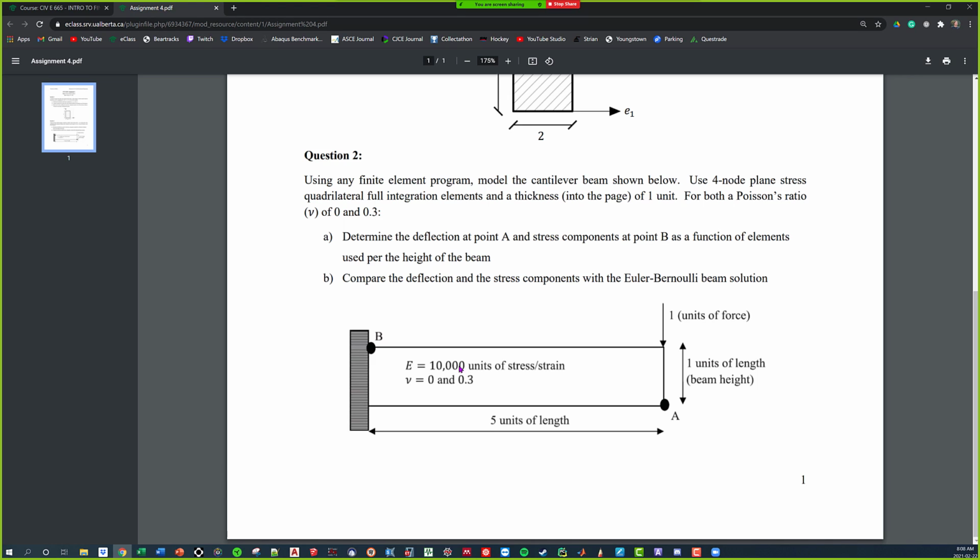So this is one of the things I've been conflicted with because I got so many questions, and the first thing that popped into my head was this would make a great final exam question. We haven't talked about the final exam yet, but that would be a really good final exam question, is why doesn't the stress S22 converge at point B? Mechanical engineers should know this. Civil engineers, we don't do a real good job at teaching why this happens. But essentially we have this, and this might be a hint for the final exam, might not be, I don't know what I'm going to pick yet, is if we look at this free surface along the beam right here, a free surface, what's the stress at a free surface? Mechanical engineers. The stress at a free surface.